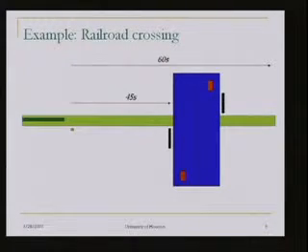So here we want the gate, so basically you have cars here. Okay, and we want the gate to be completely moved down before the train, indicated by this darker green rectangle, arrives at the intersection. So here there's a small sensor that detects the approach of a train. So once the train is detected by the sensor, then it sends a signal to the gate controller, which is going to lower the gate. Okay, so we want the gate to be completely down before the train arrives at the crossing, because if not, the car may try to continue, beat the intersection.